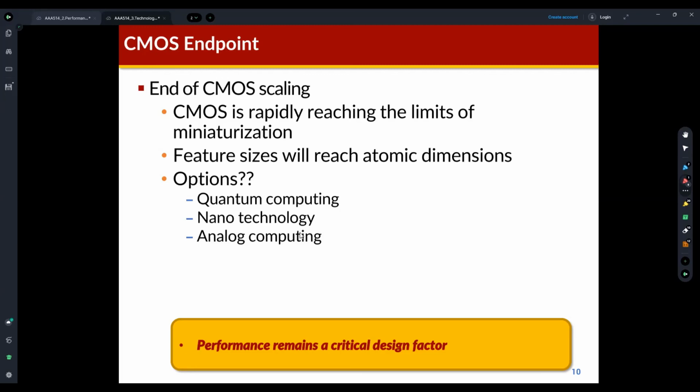With CMOS scaling, we can use better transistors, which means we can increase the performance of the processor more easily. Also, we can reduce the power consumption. Usually dynamic power consumption, but static power is very critical, and static power is actually increasing. So this is very critical for the performance of a processor. But Moore's law is ending, so it's very difficult to apply smaller transistors.